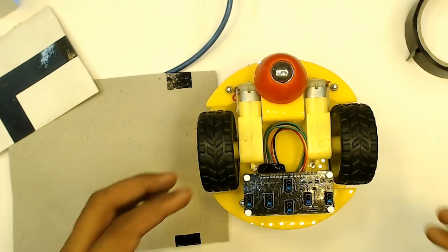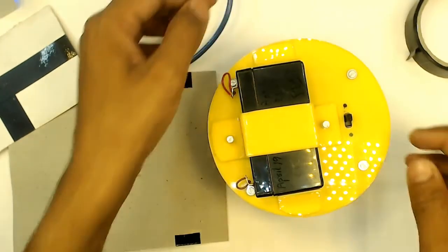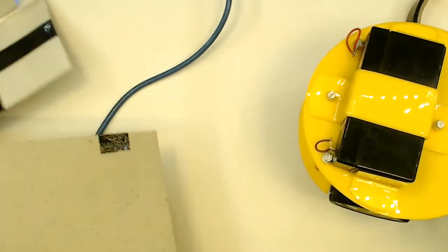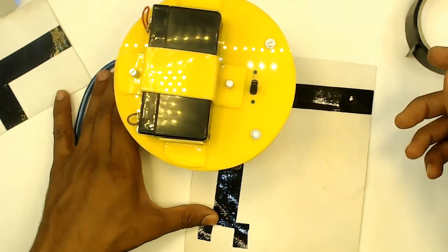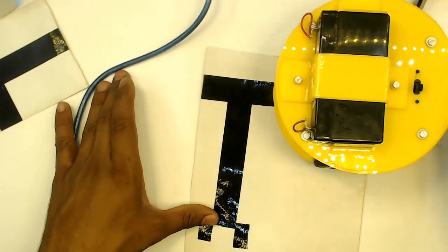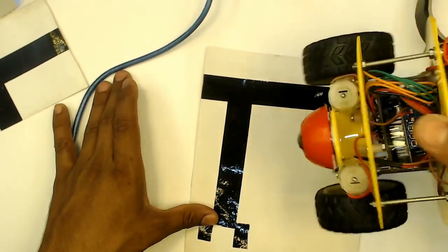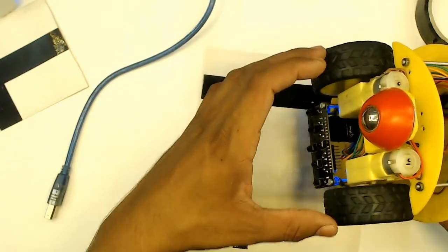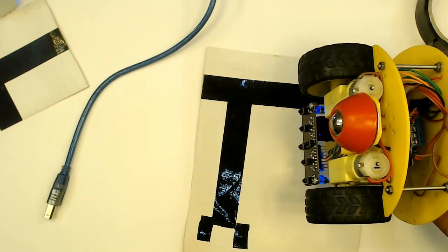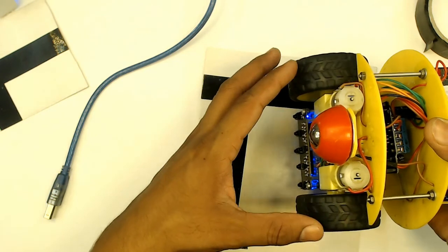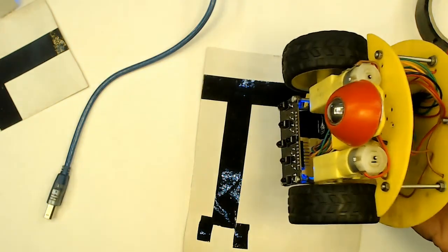For instance, if I'm connecting this motor and if I try to roll it, as you can see, it's moving pretty much in a straight direction. So you need to go for a couple of iterations first of all, and then you will find which motor is rotating with a greater speed and which is rotating with a smaller speed. And depending upon a couple of iterations, you need to finally take a decision whether to increase or decrease the speed. But I would recommend you keep the speed a little bit less during the testing phase.